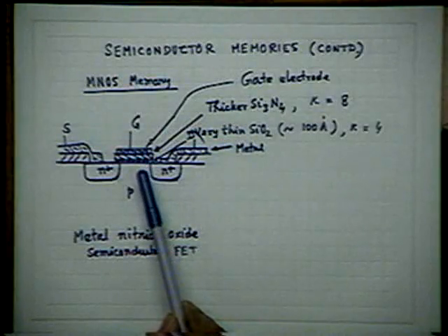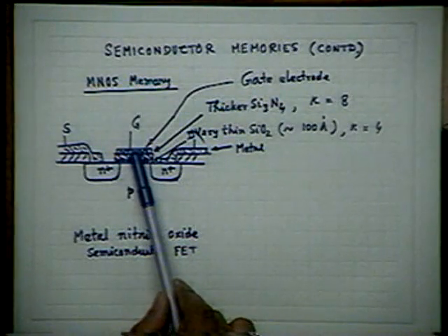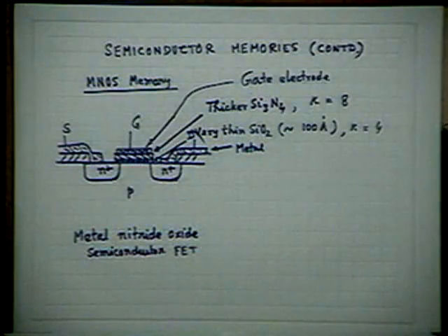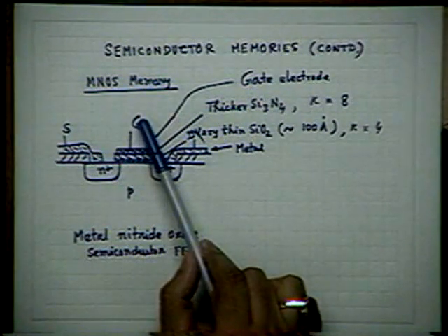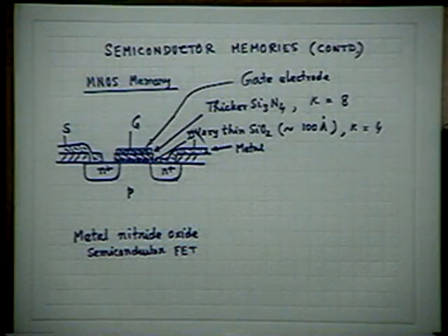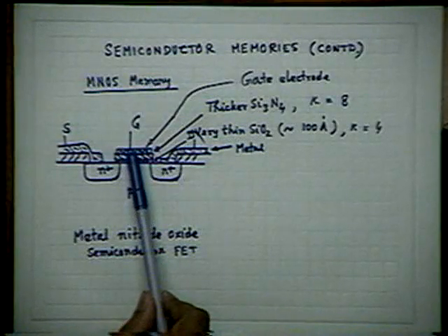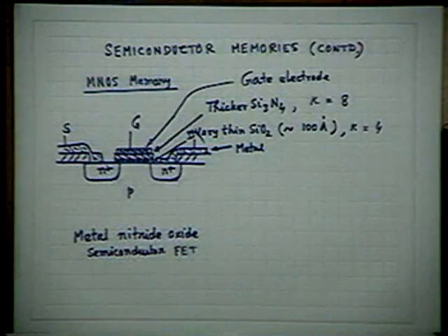And that will cause, as I told you, tunneling, because the barrier is so thin and there is a strong electric field inside. There will be tunneling of carriers from the substrate into the dielectric. Because you have applied a gate bias, which is usually positive for nMOS, electrons will tunnel from the substrate, in fact from the inversion layer, into the dielectric.